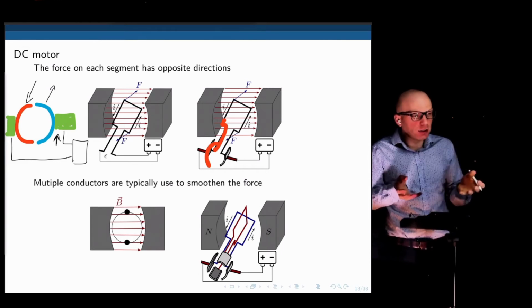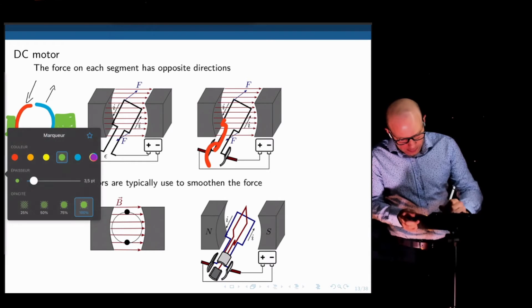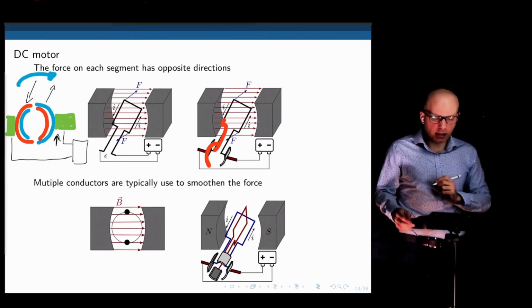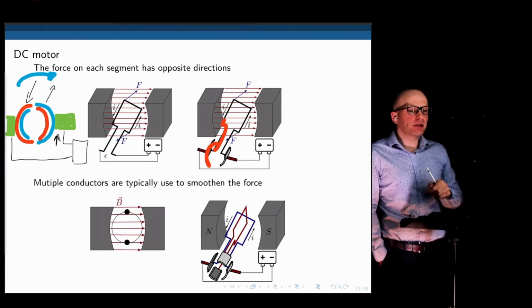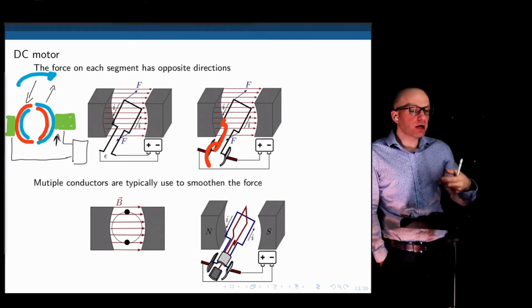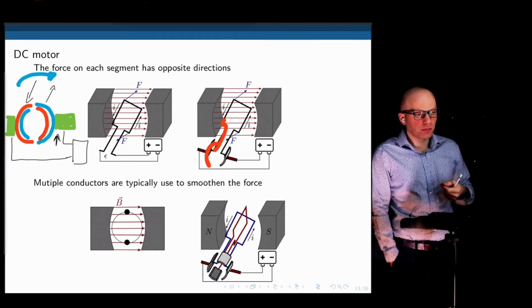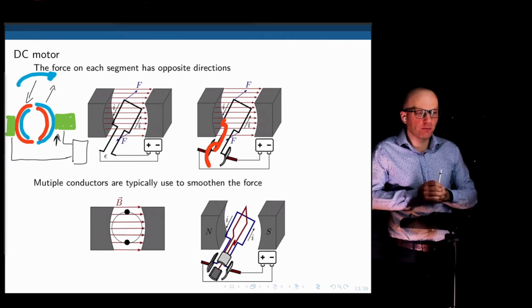It will automatically reverse, because when the red part rotates and the system becomes like this, now it rotates, let's say 90 degrees. Now you see that the current is going in through the red part and is coming out through the blue part. We reverse the current mechanically from a DC source. And this is very timed with the point of 0 EMF or of no torque.